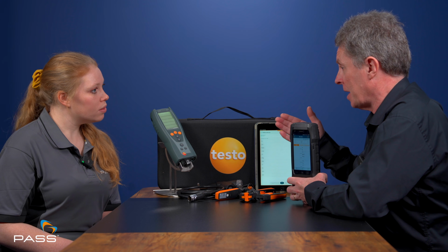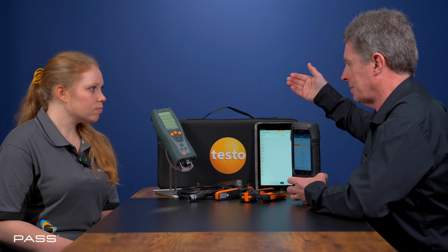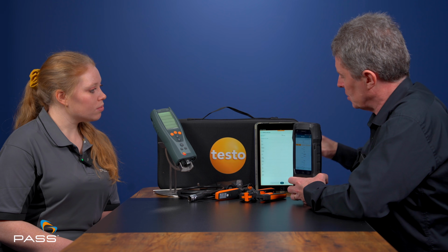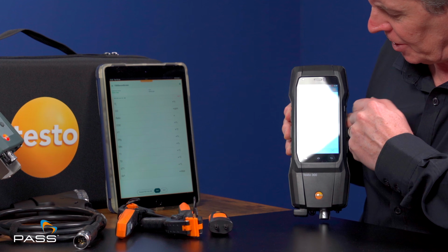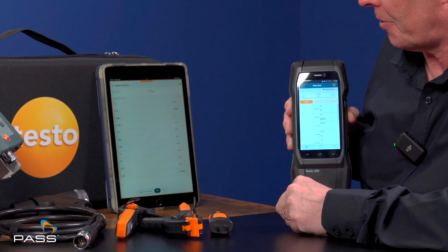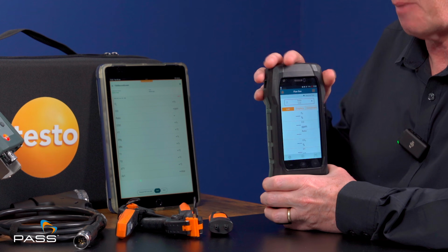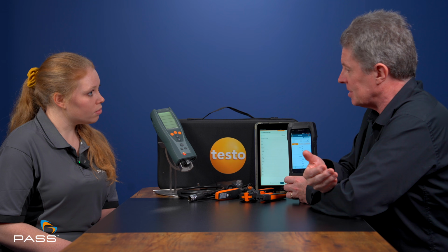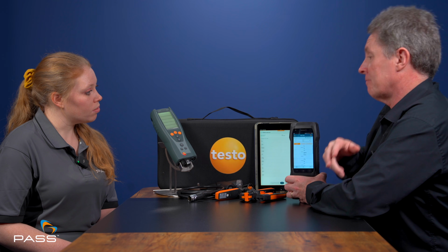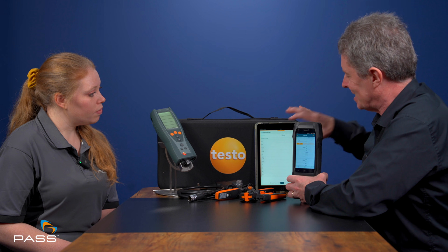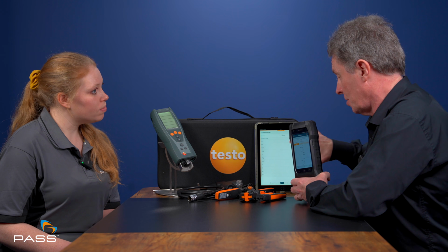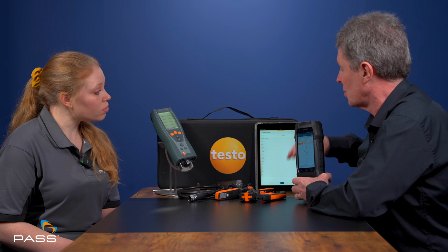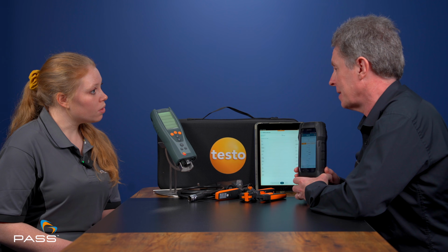So with a traditional instrument, he might be having to go backwards and forwards, look at the readings on his analyzer, do some adjustments, go back and see the results. With this, what he can do is, you can see here, we've got the screen showing the combustion readings. We've got exactly the same mirrored on here. So he can set this instrument up at the sampling point, take his mobile phone or tablet with him to wherever the burner is, do the adjustments live and be getting the information live across. So it's the ability to have that second screen of information. And obviously also within the Smart app, we can now also report on this. So we can save these readings, put them into a report and email that as a PDF to the client.